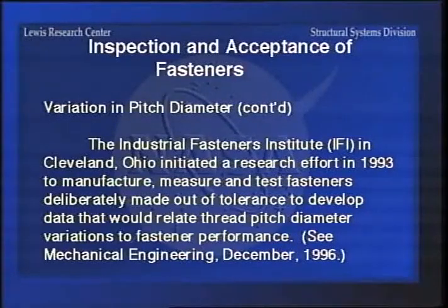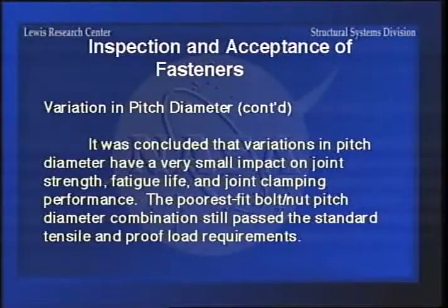And they put out an article on that in Mechanical Engineering in the December 1996 edition. The conclusion was that variations in pitch diameter don't have a very big effect on the joint strength, fatigue life, and clamping performance. In other words, it can be out of tolerance quite a bit and still pass the standard tensile and proof load requirements, which kind of surprised a lot of people.